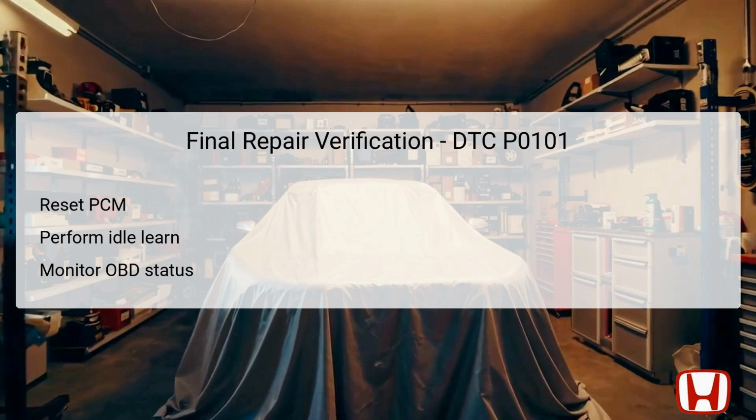Upon completing repairs, it's crucial to perform a final verification to ensure that the issue has been resolved. Begin by turning the ignition switch back to the on position and utilize the HDS to reset the powertrain control module, PCM. This step will clear any stored DTCs and allow the system to refresh. Following the reset, perform an idle learn procedure to recalibrate the system based on the new sensor readings.